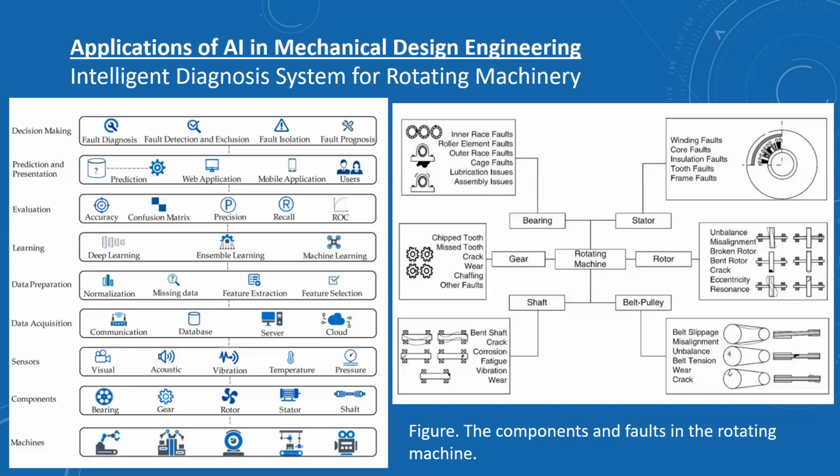Most commonly, when you are working with rotating machinery, we use FFT analyzers. I don't know how many of you are aware of it. In mechanical engineering, we use those FFT analyzers, and they give us the data in the form of a signal, so we do signal processing. If electronics people are here, they are well aware of it. Then, using the outputs from the signal processing, we find which type of defect is present, depending on the range of frequency. That type of data is possible only with the help of sensors. Without sensors, we cannot record the data.